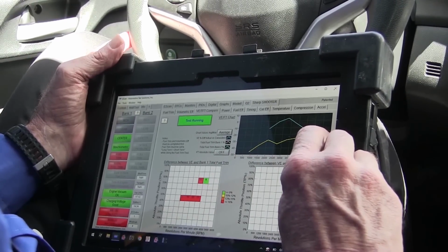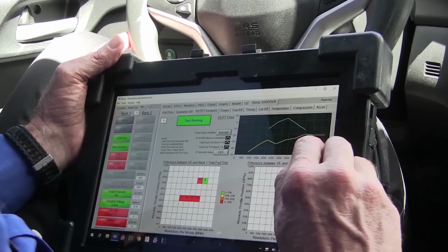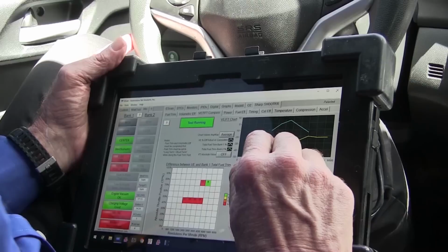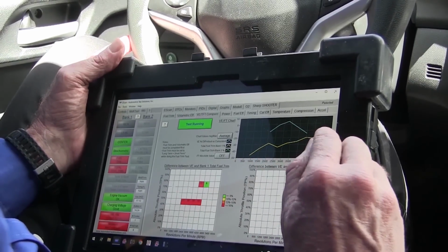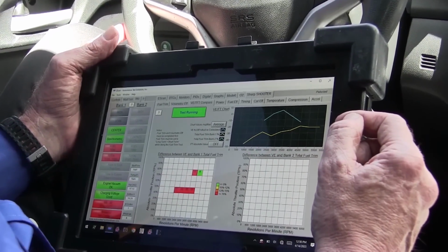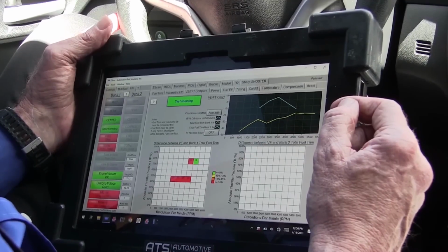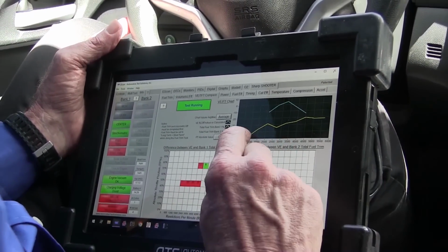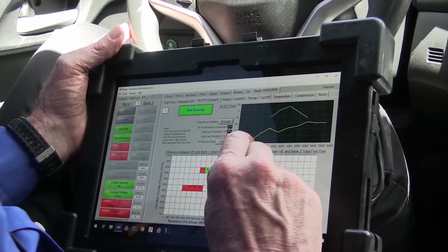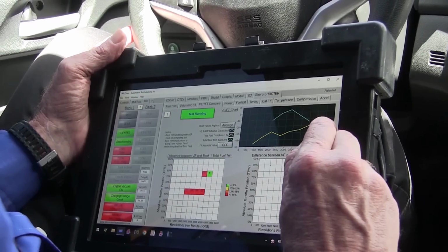And here we're basically at minus 45, moving to minus 20. So this isn't linear, it's not minus 40 to minus 40. My trim got better as I revved it. Now, if I had a problem where the injectors had a problem and they were the wrong injectors in the car, which I've seen from time to time, this trim would be linear. It would be 40 to 40, but it wouldn't be 40 to minus 20.